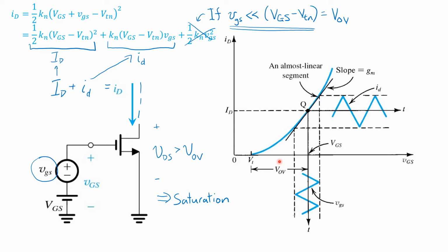This then is the basis of all small signal analysis. We first establish an operating point, and then we make a linear approximation at that operating point in order to allow for linear analysis. And as long as the superimposed signals are small enough, we can use the linear approximation to relate deviations in voltage and current away from the operating point at various points in the circuit.